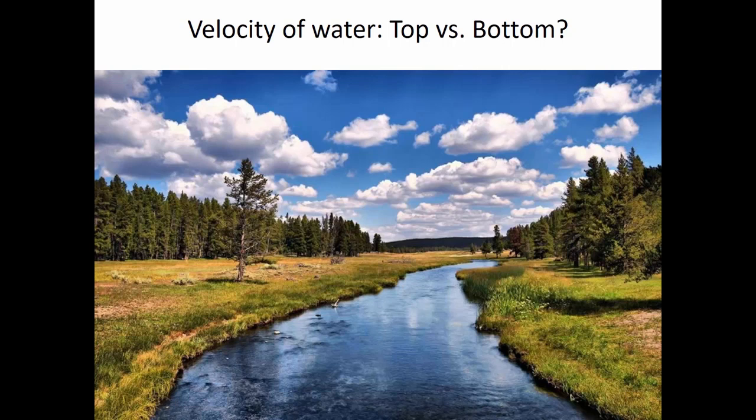The speed of the movement of the water isn't the same at every depth. It would be wrong if we assumed the water was all going the same speed at the top and at the bottom. More realistically, the water that's very close to the bottom is going slow, and it progressively increases in speed so that there is a velocity profile that looks like this shape.